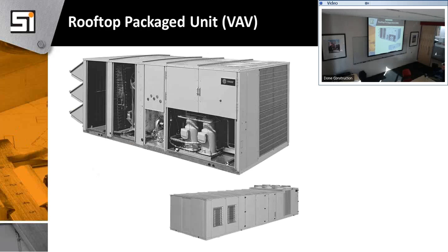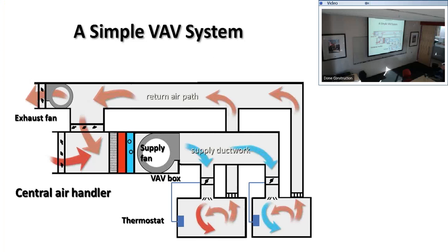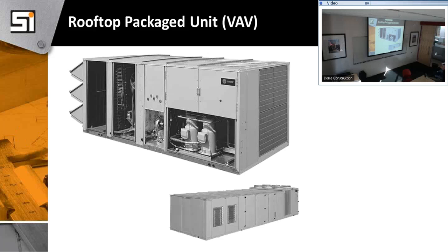So again, we're saving energy. We're not constant volume reheat. So you have a VAV box, and I'll have pictures of that throttle air back. I'll pull up a picture of that to show more of it. This is serving multiple zones, multiple thermostats, like in a VAV, multiple kinds of businesses. Yeah, those typically have to have the reheat coils on each zone, correct?